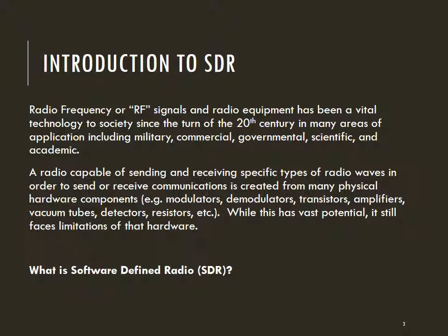So what is software-defined radio? SDR, as its name implies, is defined by software rather than by hardware. A hardware-defined radio receiver for a set range of frequencies using a set modulation method could only ever receive those specific signals, whereas SDR has the capability to virtualize many of the hardware components and circuit paths that process the RF signals and can be changed or configured dynamically on the fly, such as changing modulation techniques, frequency ranges, filters, etc.